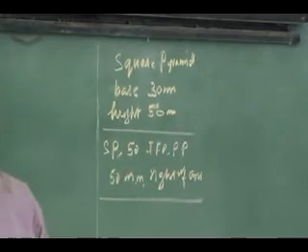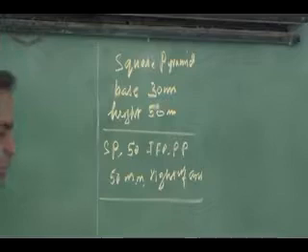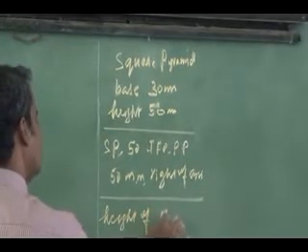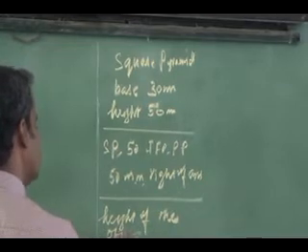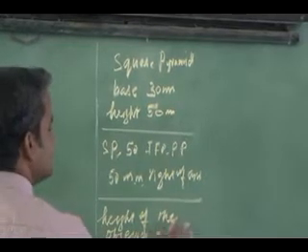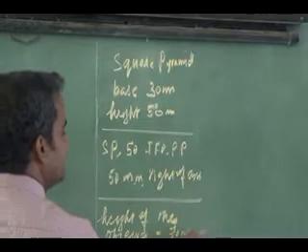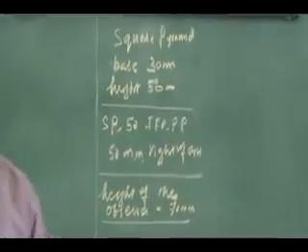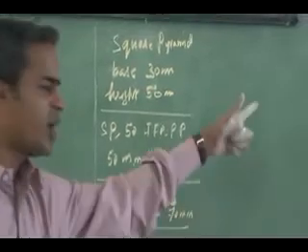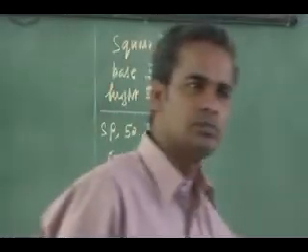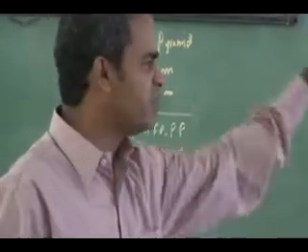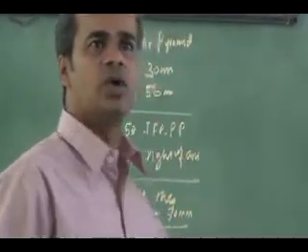If the height of the observer is 70 mm, what is this? It is the above distance of the station point. Instead of the above distance, I have the height of the observer. Quickly draw the layout and try to draw the perspective view. You can do it, same procedure.